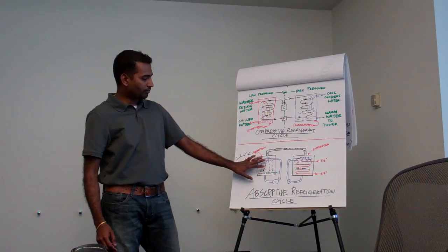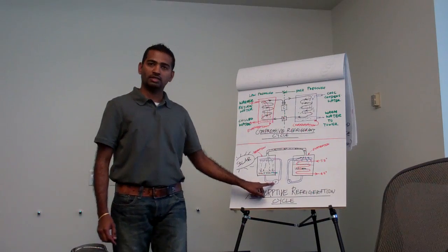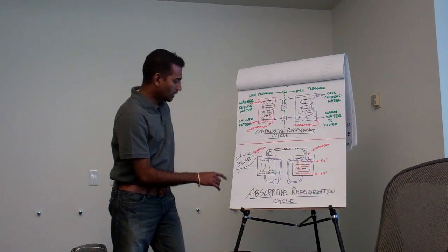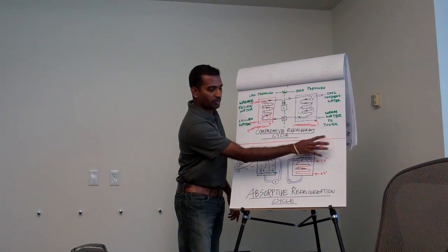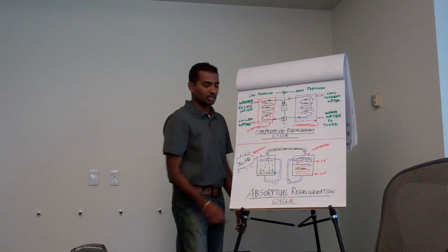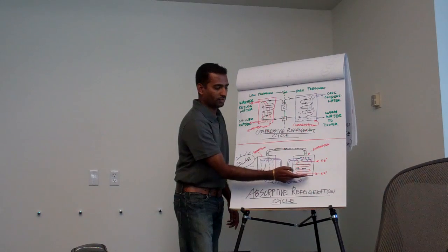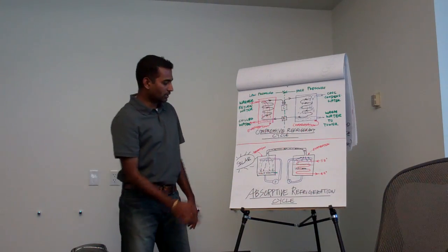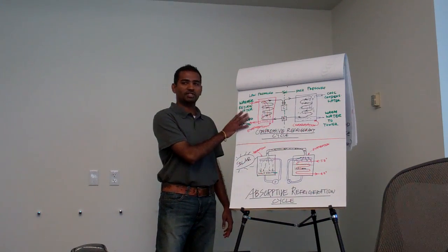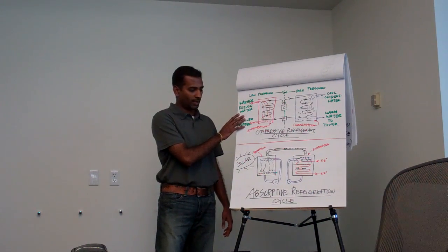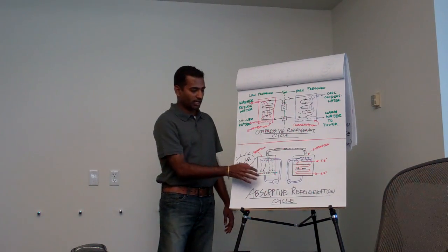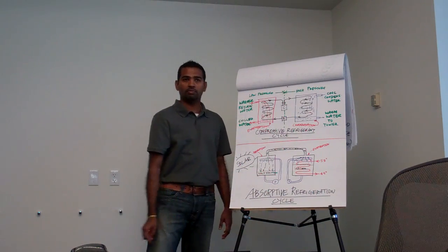And we pressurize this and we put a pump to make this process go faster. And on this side, evaporation takes place, so you go ahead and put your condensing coil heat exchange. That's where you supply 55 and it becomes 45. Absorptive refrigeration is not as efficient as compressive. But the advantage here is you could use solar to enhance this process, rather than just the pump.